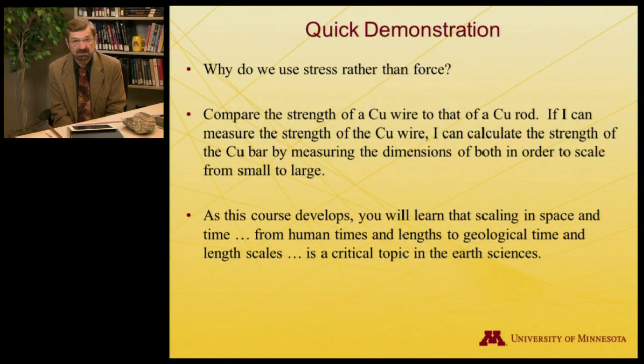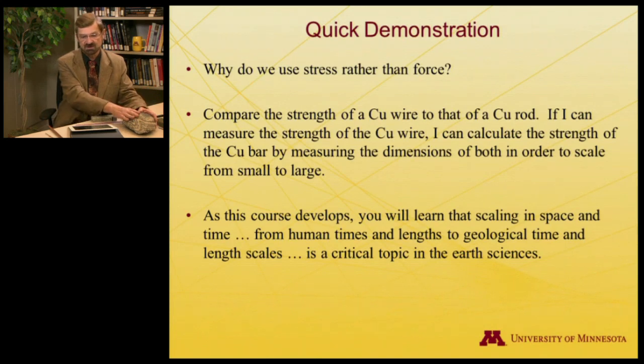So the important point of this demonstration is that stress really is the critical factor. If we want to understand how to take what we learn in the lab and apply it to what goes on in the earth, we need to use stresses rather than forces. And stresses, again, are simply forces normalized by the cross-sectional area. It's a way of saying that the size of the object that we're trying to deal with really does matter. And so we want to get to a fundamental material property, that is the strength or the stress required to deform it.